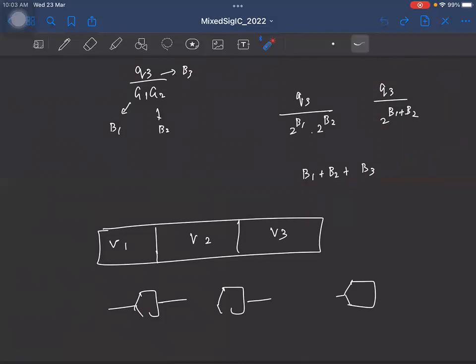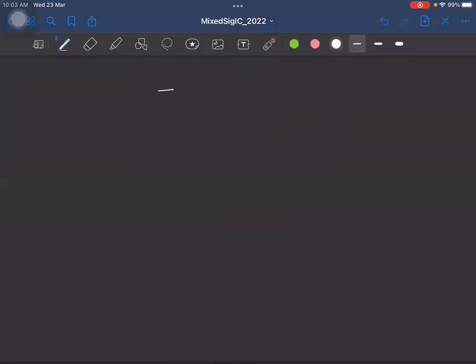You don't need an adder, isn't it? You just need to concatenate, right? So you have 2 bits, and I have 3 bits coming from the second ADC, let us say. I'll just wire it in such a way that these 2 are the MSB bits and these 3 are the LSB bits, and send it to the output. So this is my MSB, this is MSB minus 1 and so on. The point is there is no need for an adder in this case. Is that clear?